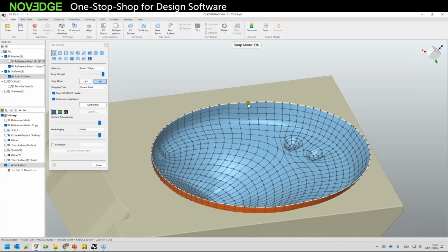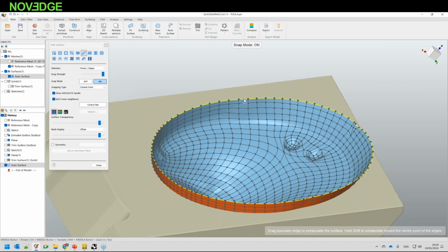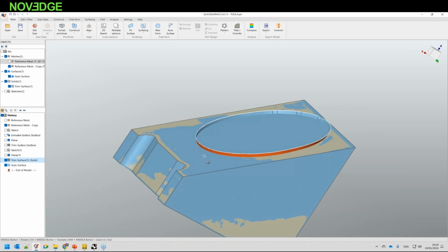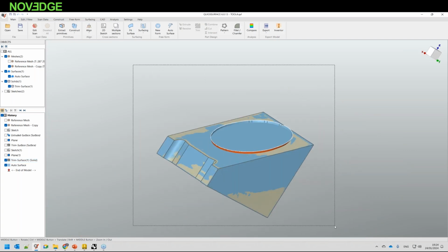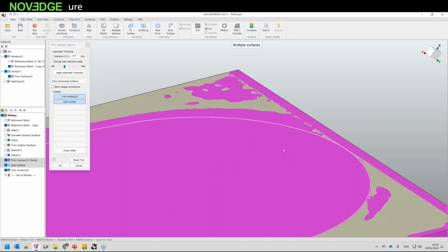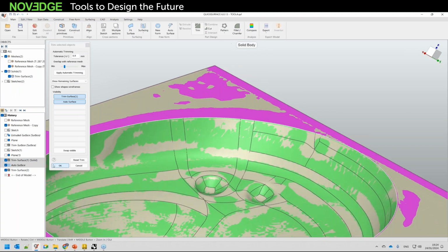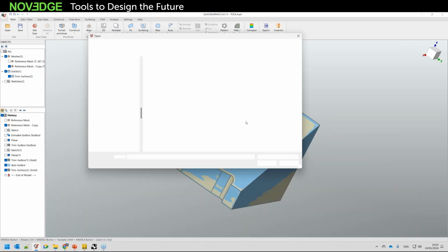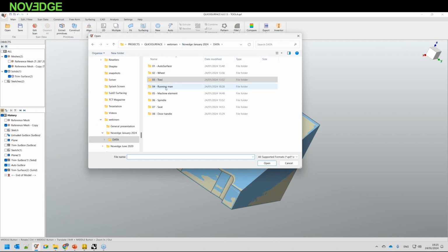What the next step should be in this project, I can use our extrapolate function, which means that if I just take something, it will just take the boundary and move it out of our extent. Why I did this, again, this is the simplest way to complete the project. I'll just select everything and we'll use our mutual trimming operations. Just cut off what is not needed, press OK, and I completed my job here. This was the other very simple example.